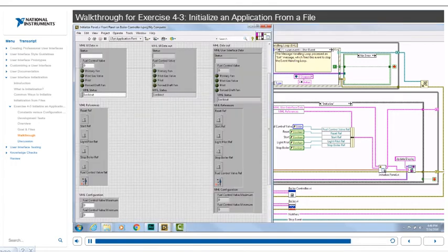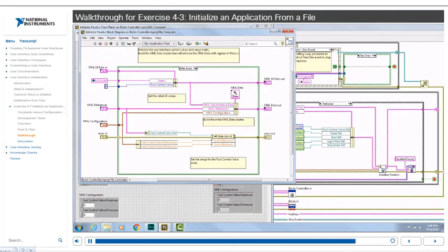cluttered. If we look inside of this VI, here's where we can see that we take the message handling loop configuration input, read the maximum and minimum values, and set those as the maximum and minimum properties for the scale of the fuel control valve.